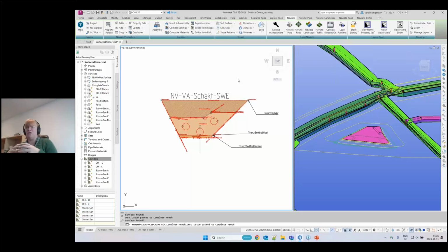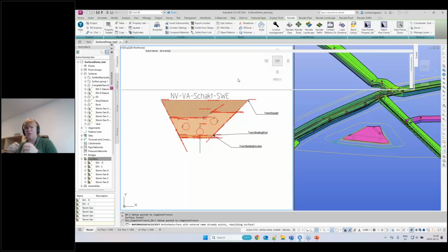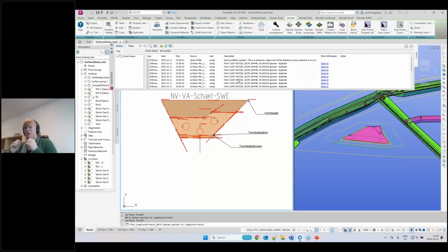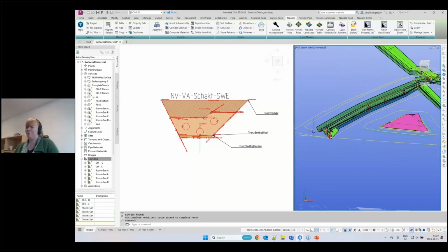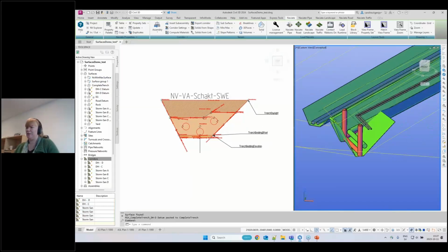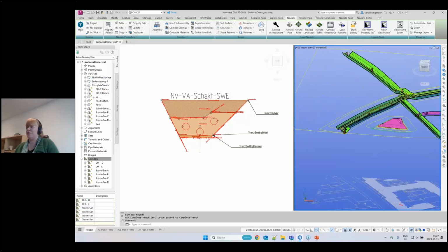And this is important when you use surfaces. If you've started using links to your surface, don't remove the surface. Empty the information in it, surface properties, and re-import information to that. But keep the name, keep the object, and it will be so much better for you. And now my surface is updated. And you can see that I have the sloping there. So MinMax to create combinations.